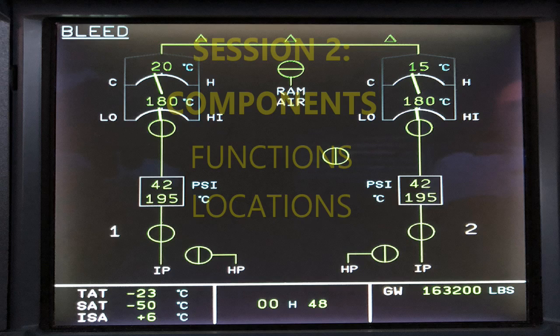Okay. All right. So, just a little bit of a tip, if you will. There are nut plate retainers, and those nut plate retainers are not physically attached to the mounting frame, so just be careful because they're not attached. If you are trying to remove things, that retainer could possibly fall into the pylon cavity and mess some things up, so you don't want to have that happen.